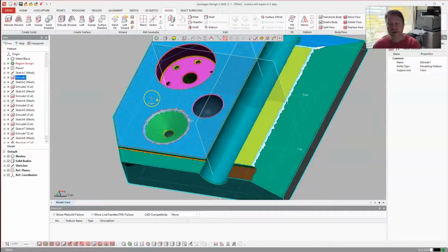All these little odd shapes are polylines that represent the points that cut through that plane. So in order to do the same thing here, if we could easily make a plane right down the middle, we can have Geomagic Design X create us a sketch of the profile in there. I gave you guys all these hints. Well, if I could do half of the profile and the revolve cut, I can have that one. How do we get there? We could draw on any of the planes. Let's create a plane there. So we go to reference geometry, plane.